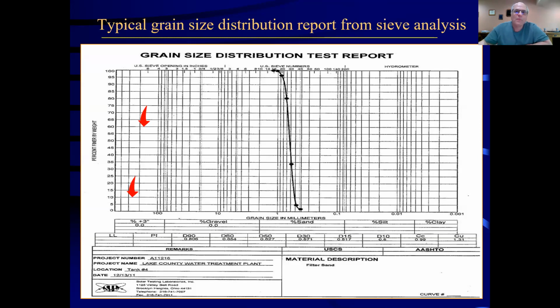So what they do is measure out this 100-gram sample and run it through the sieves like we mentioned. They plot it out on this logarithmic graph. You'll notice in the middle of the graph there's an inverted S-shaped curve, and on that S-shaped curve there are dots. There's 1, 2, 3, 4, 5, 6, 7 dots on there. Those 7 dots stand for a pan, one of those sieve pans that you saw in the previous picture. Obviously, for this test, they used 7 sieve pans.